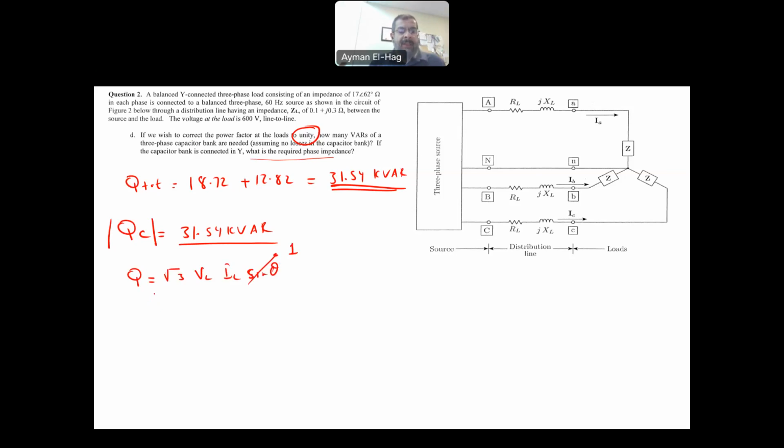Okay, and we can also convert the current in terms of the voltage, so we will end up having this formula for Q with the current and the voltage. So here basically this is your impedance, this is 1 over omega C, and this is your current I, and this is your voltage V. So the current is equal to the voltage divided by 1 over omega C, so it's equal to V times omega C.